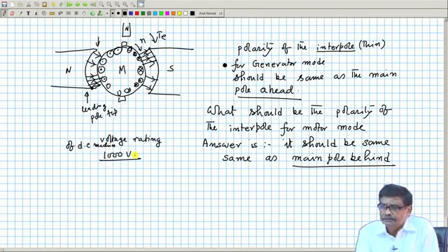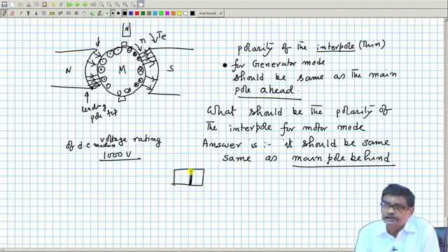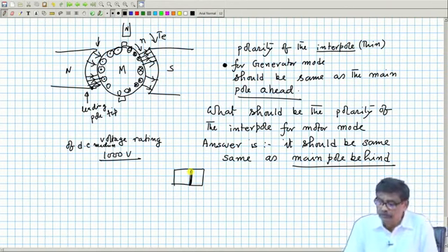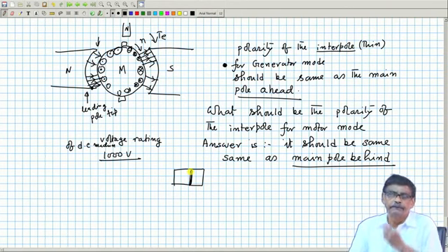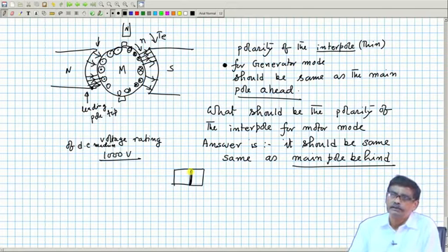So, mica has a breakdown voltage of its own, and two commutator segments side by side with a thin layer of insulation, with large voltage, means the voltage existing between the commutator segments will also be large and the machine will fail. Anyway, with this note I stop today. We will continue with this, and in the next class I will discuss the brush shift that can be given to a DC machine to improve commutation. That will be in the next class. Thank you.